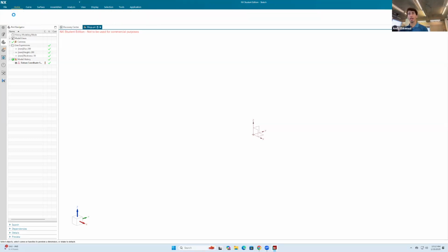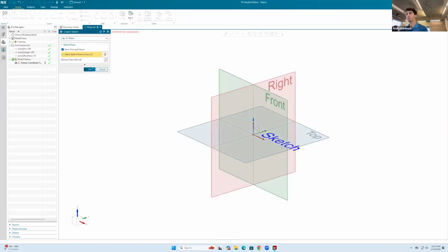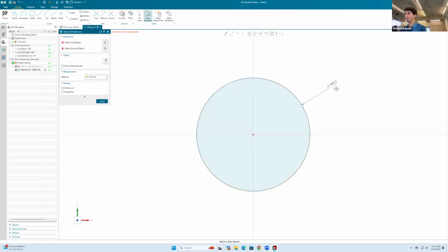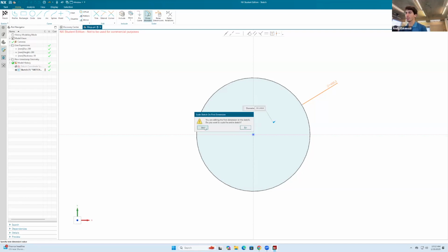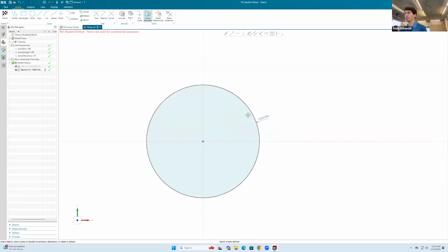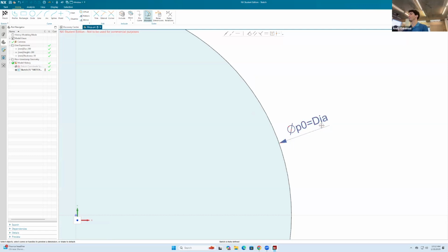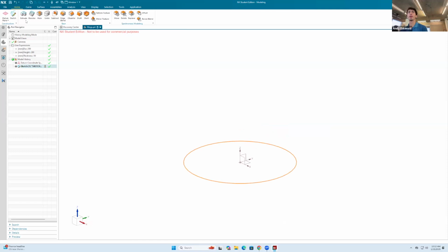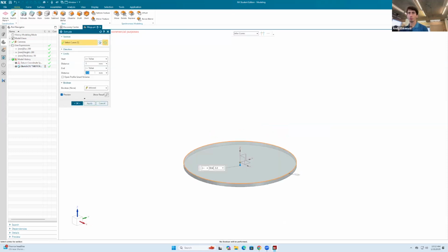So click here on Sketch. I'll go here to top, and I'll do a circle. Now I'll click on letter D. And now where it says 490, click on the equal sign and write dia. And then say yes. Excellent. So now you see there's no number anymore. It's dia that's going to control the dimension of that circle. So that's great. Now we click on finish, and then we do an extrusion.